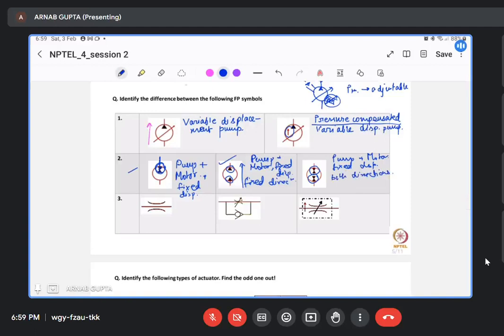Okay, so I hope you understood. In the first one, the liquid can either flow in or flow out from this end. In the second case, the liquid has to flow in from this end and has to flow out from this end, not the other way around. Any other possibility is not there. While in the third case, liquid can flow in or out, in case of a pump or a motor, from either end. So if it is working like a bidirectional pump, this is also known as a bidirectional pump or motor. This is unidirectional since it has one particular direction.